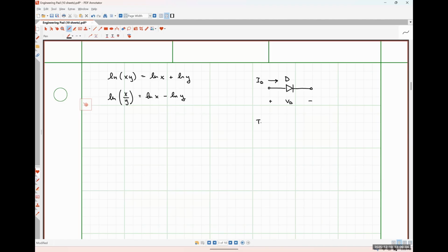And the relationship between voltage and current in a diode is this mathematical relationship. So our diode current, ID, is going to be equal to IS. So this is our saturation current. This is something that we can find on the data sheet usually. It's typically very, very small, so on the order of nanoamperes to picoamperes. Okay. So we have IS times the exponential of